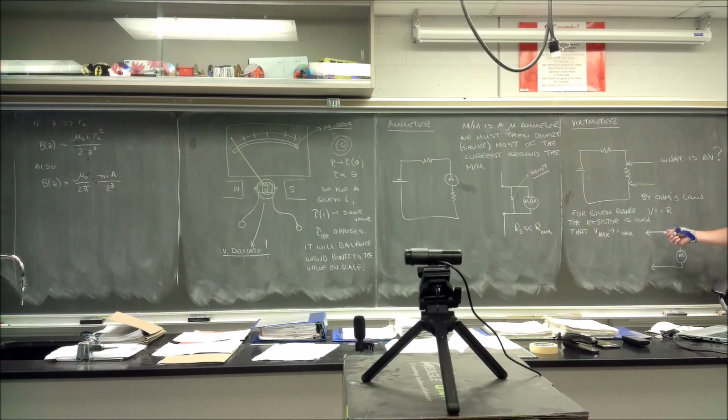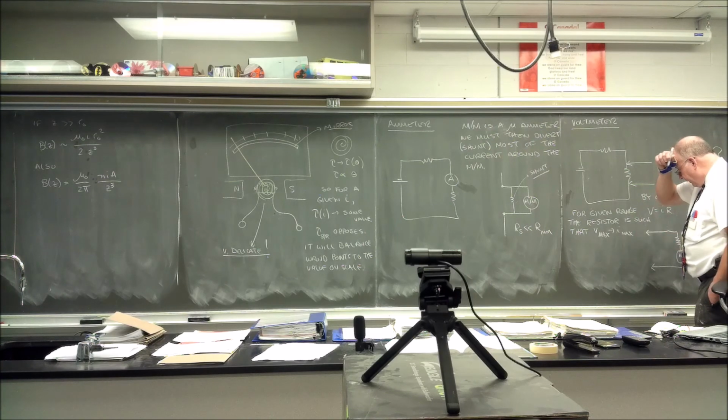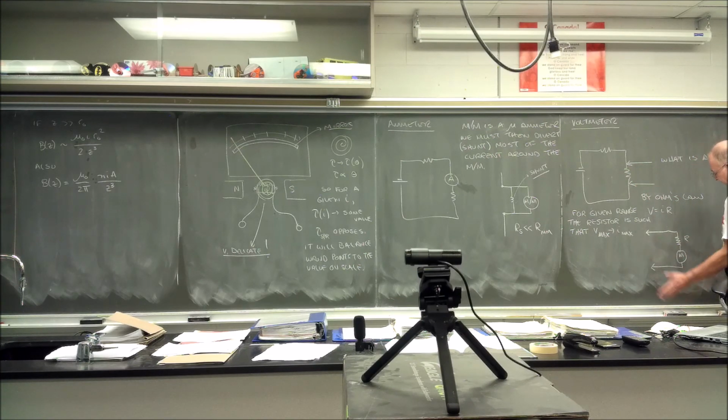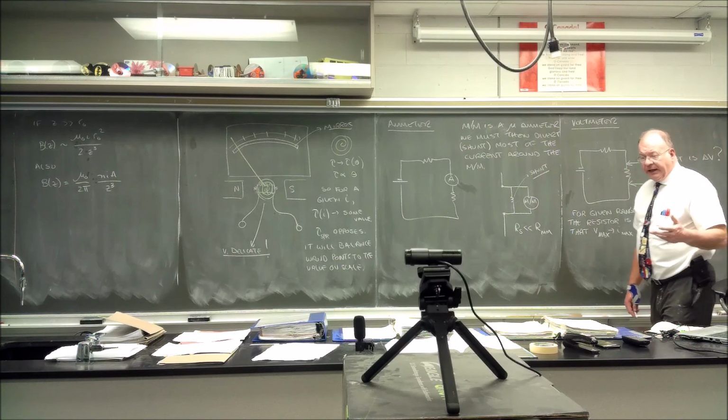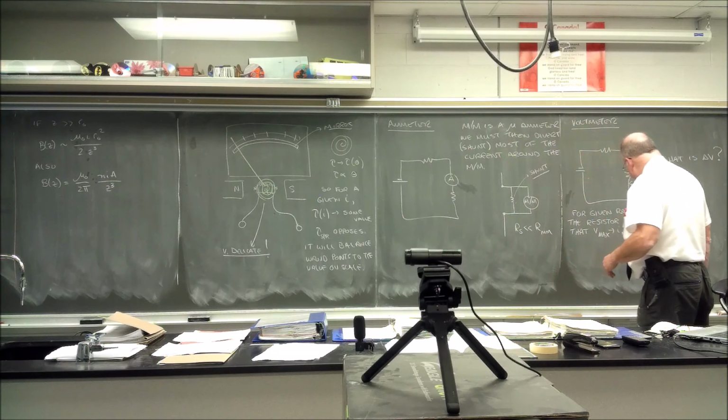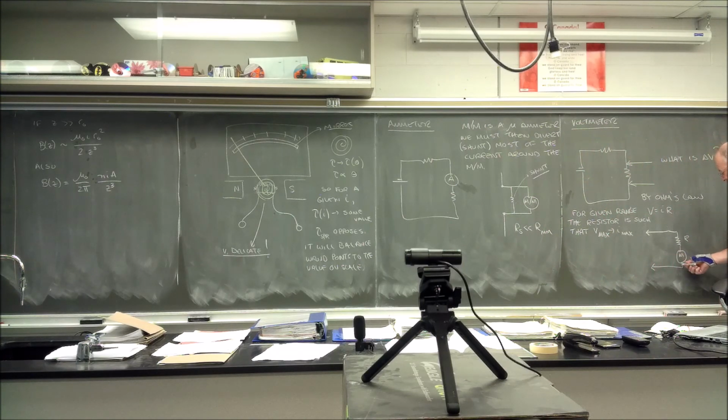If you choose a low scale, say the voltage here is 10 volts and you put a 1 volt scale, then the current will be too high and the meter will slam over. You have to switch it. You can't do that without care or the meter will be damaged, but you can get away with a little bit. And whatever it reads here, this current is small.